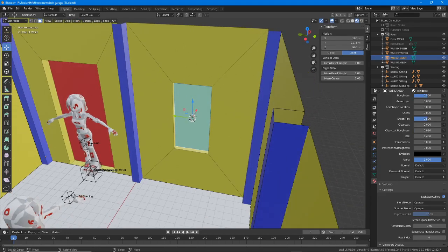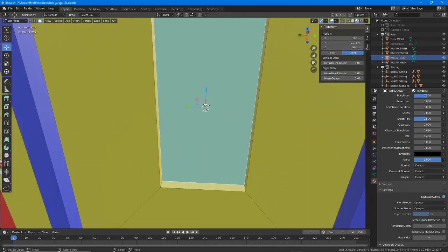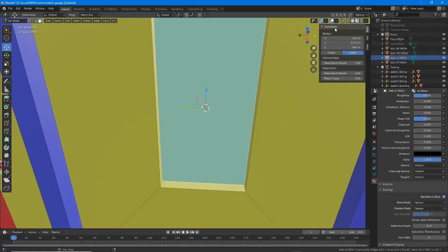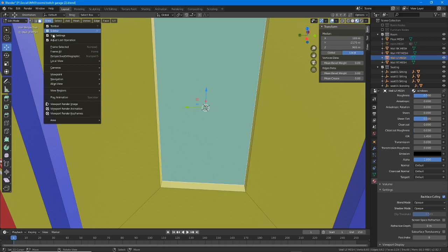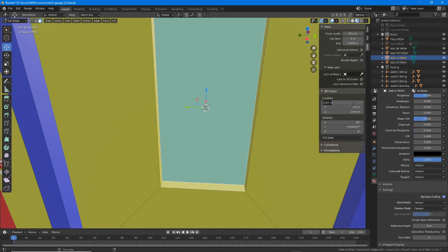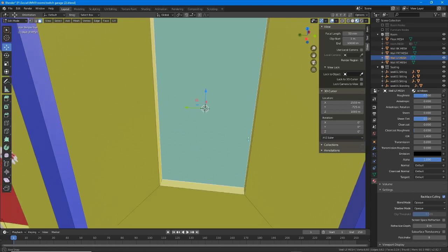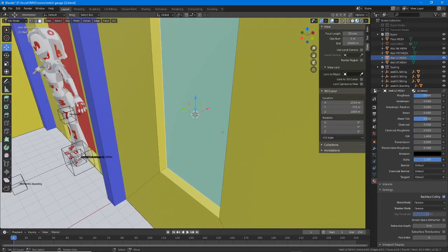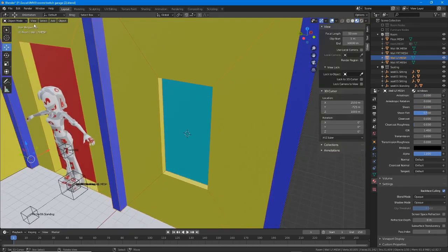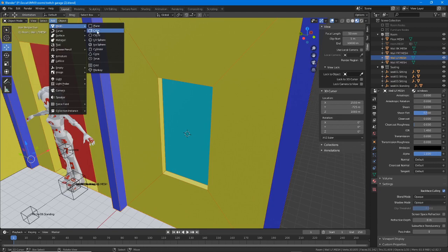And it moves the cursor into position, but we might want to also reorientate it because it's off kilter. So in the sidebar, so we've already got that visible. We want to view 3D cursor. Oh, we don't want to change its position. What we want to do is change its rotation. Just to double check. That just straightens it up, and then exit edit mode, and then add mesh cube.